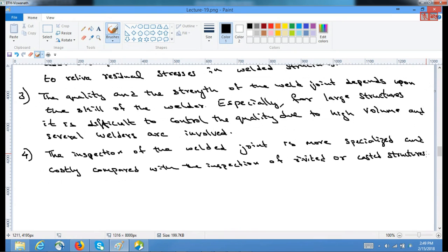Since the outside doesn't tell you anything, you need a kind of X-ray diffraction techniques to inspect the quality of the weld, whereas for the riveted or other things, a manual inspection is sufficient. So not only the skilled labor, but also to do the quality check, it would be costly. And the execution is easier, but quality check is the costlier part in the welded things.